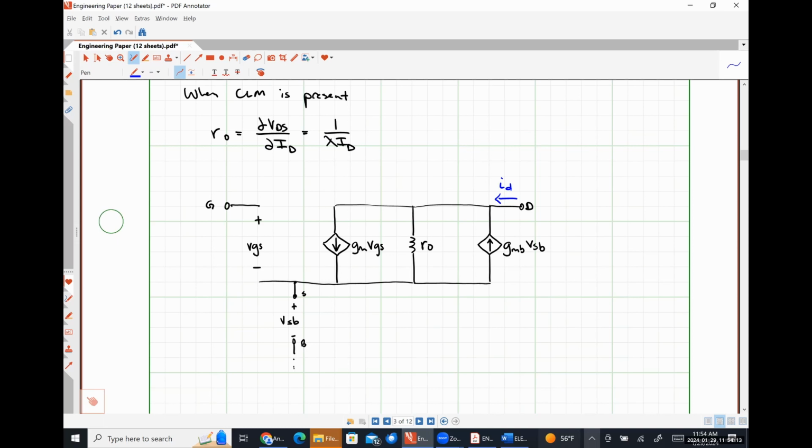All right. So we have all of the different pieces and parts here. One thing that I want to potentially clarify in case it was not obvious, all of our small signal parameters, our transconductances, our resistances, and all of that kind of stuff are set by the values of our DC operating point, right? So we have to know what's going on at DC in order to have any clue of what's going on at small signal or AC.